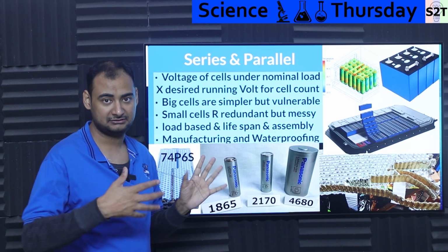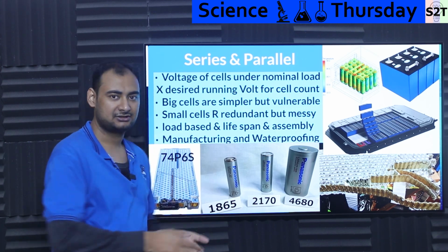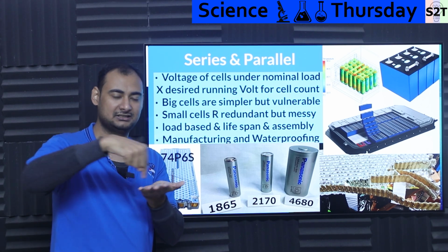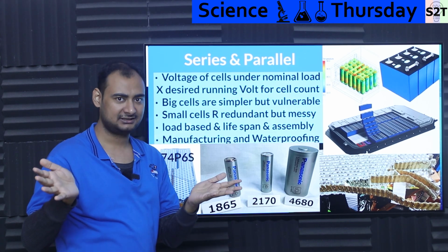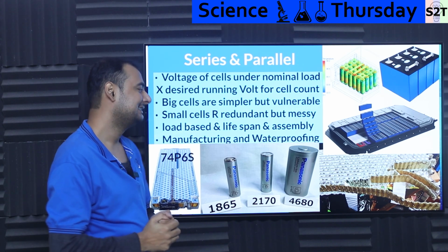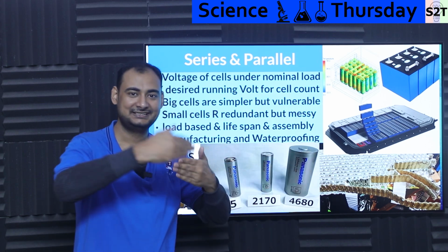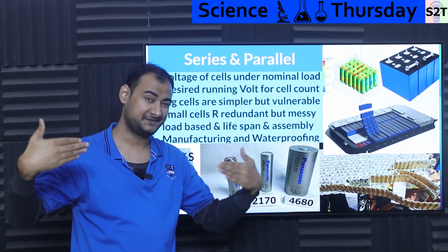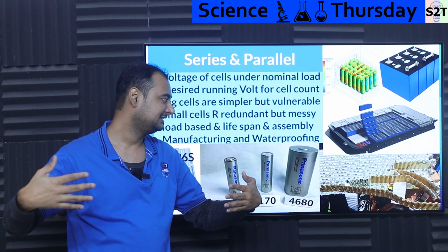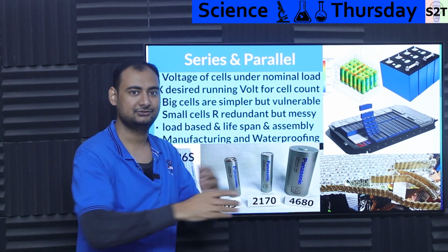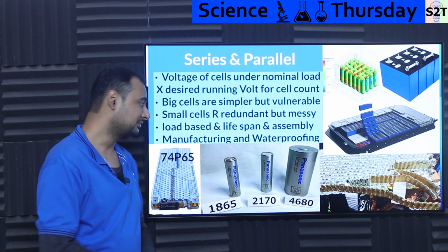Not only in terms of the wiring and all that, because they did figure out, hey, aluminum plate, not the conductor plate, that's it. And just spot weld fuse wire. They figured that part out, cool. But the problem is, it's messy in terms of cooling. Cooling here is far easier compared to cooling like this, where they have to serpentine a very specific type of plastic, almost, that is conductive enough for thermal transfer, going serpentine around it to cool it. So you have to balance all that.